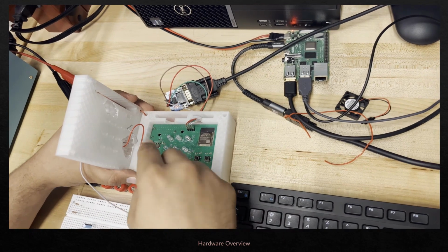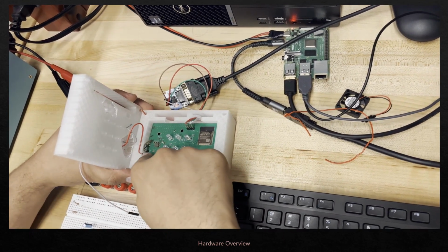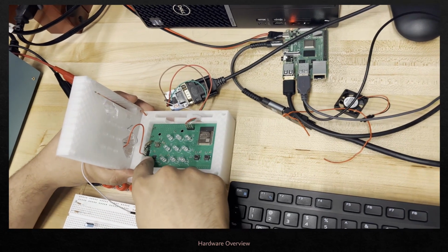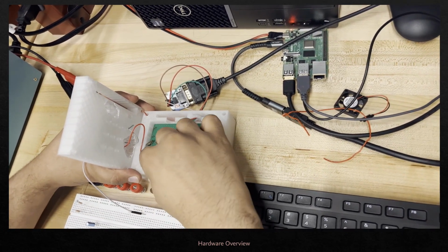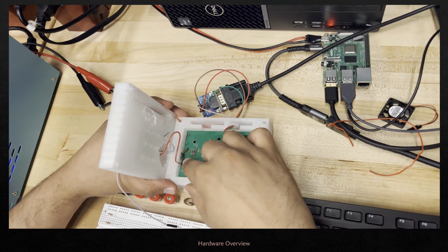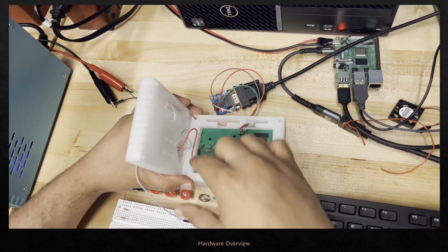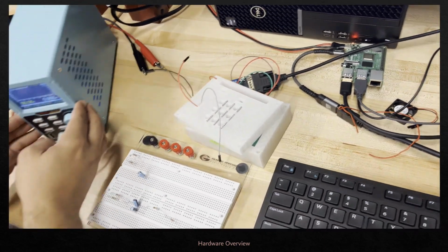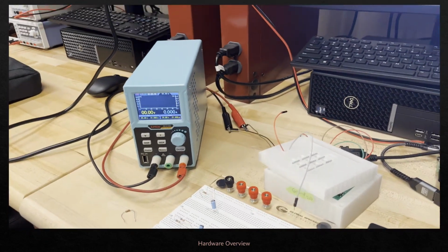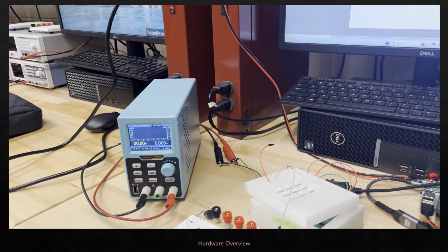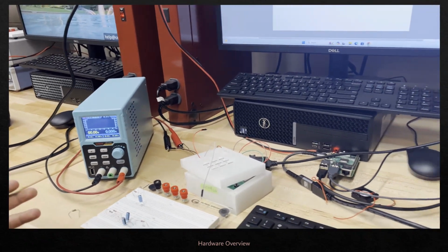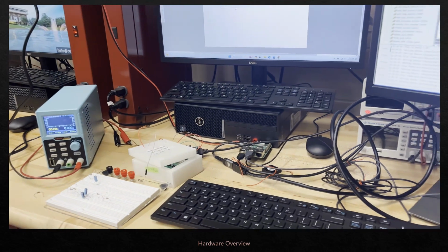On this left side here, these are all connected to the sensors. These 2 pins are used for the user's power supply. This is V in, and then the ground. On the other side, the 2 pins will be the ground, and then that will be connected to the load circuit or the user circuit. What we have over here is a power supply that the user could be using. We're going to be using this for our test runs to demonstrate the user's power supply. And that is how all the communication for the hardware is connected.